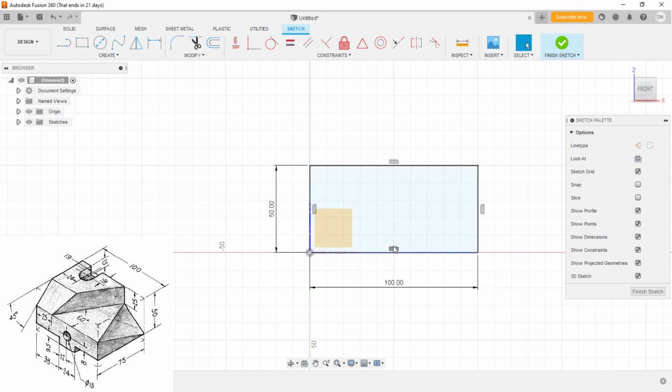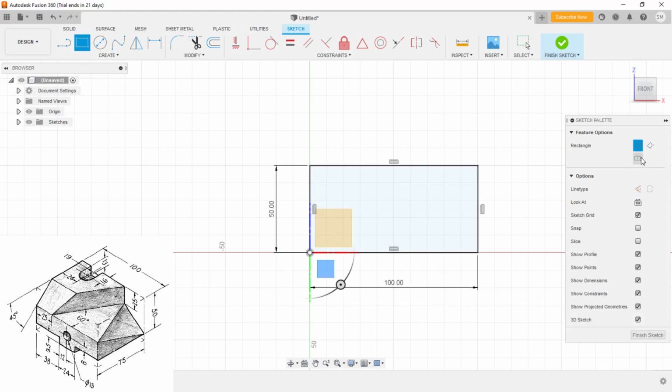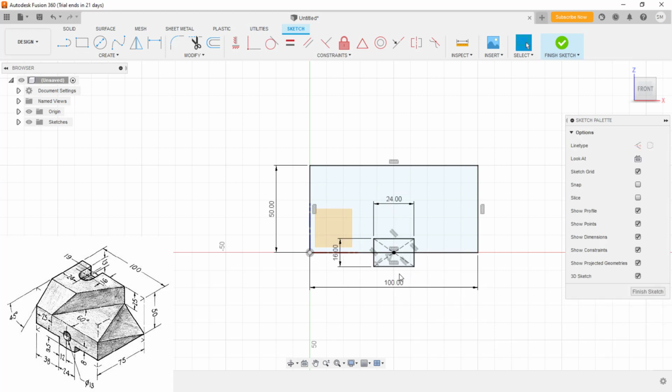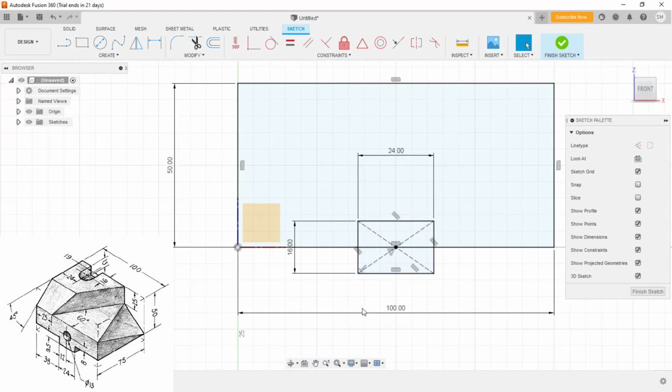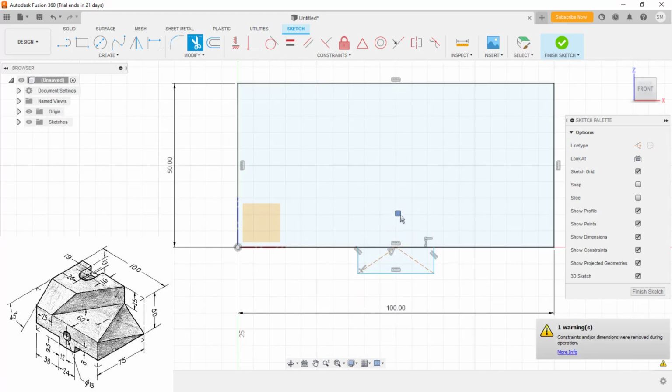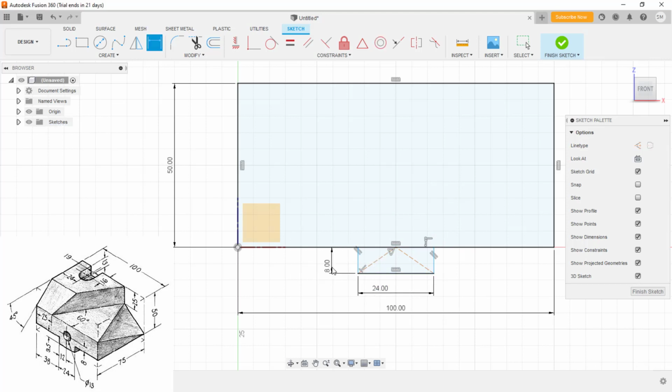And now I'll add this as well. At the bottom we have this rectangle extrude. Now, I'll use the center rectangle this time. A shortcut, activate 16 and 24, and I need to trim the top portion. Use the trim tool, T shortcut, and now this dimension is 24 and this is given. It's not exactly 9, I'll change it later. So this is 38.